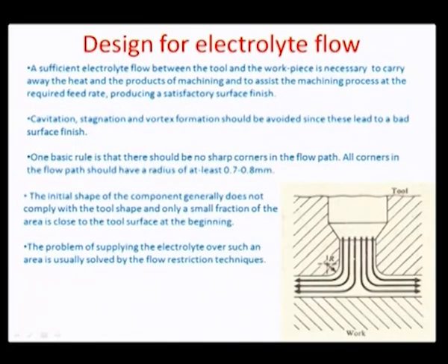So the other aspect I would like to illustrate for the ECM process is the design for electrolyte flow. One aspect we have already discussed is how the velocity and pressure could be calculated. The other very important part of the layout that we have to plan is how you flow in the electrolyte to begin with.